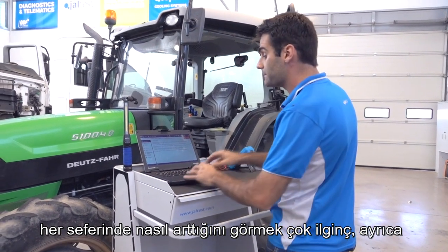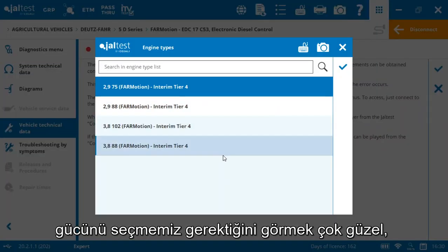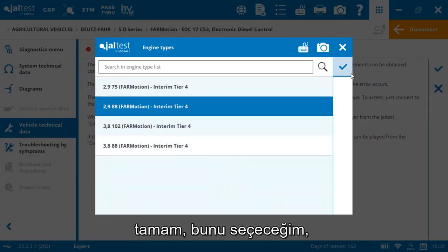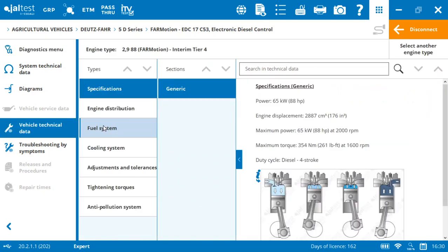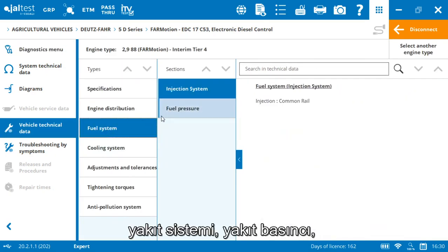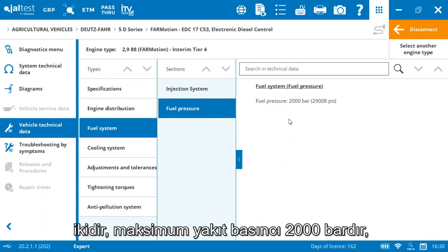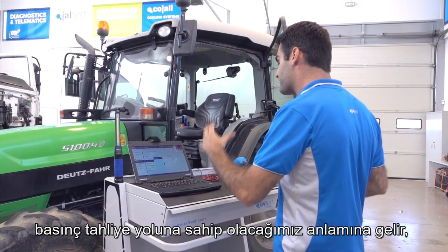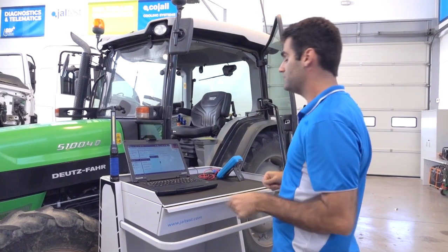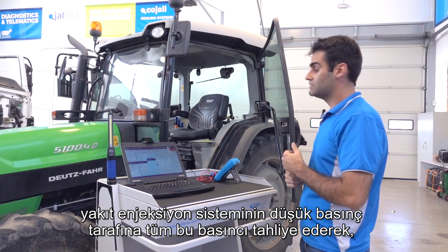Also very nice to see in vehicle technical data, we need to select the horsepower. Okay, I'm going to select this one. It's very important to see here. It's included for free in Jaltest, it comes with your license. In the fuel system, fuel pressure, I see that this engine has a maximum fuel pressure of 2000 bars. It means that above this pressure, we will have the pressure relief valve that we talked about before, relieving all this pressure to the low pressure side of the fuel injection system.